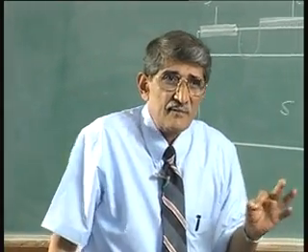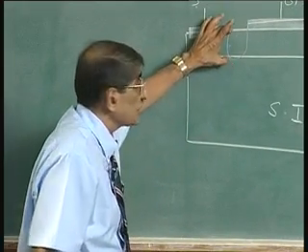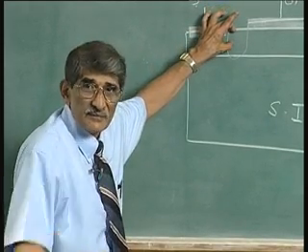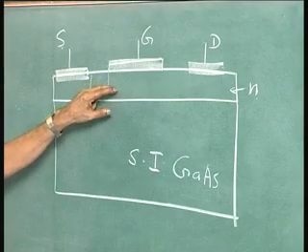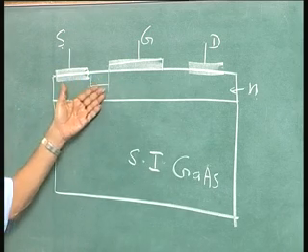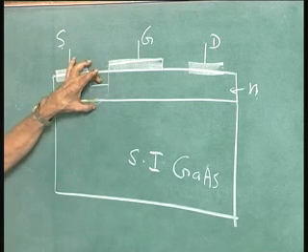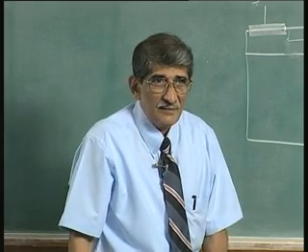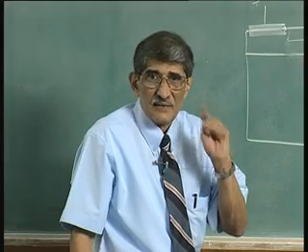This is one of the difficulties that people are facing when making this type of device, particularly if this layer becomes thinner and thinner, because after all, as we said, the potential here is equal to 2/3 of Eg at the most. Correspondingly, how much is the depletion layer depends upon the doping here. So, if I have a thickness only that much, maybe you can say there is still some opening path, it will lead to increase in resistance. But if the thickness of this layer is this thin, the entire layer is depleted. There is no path between source and the channel. So, the MOSFET will not work. It is just like the MOSFET without an inversion layer connecting the source and the channel.